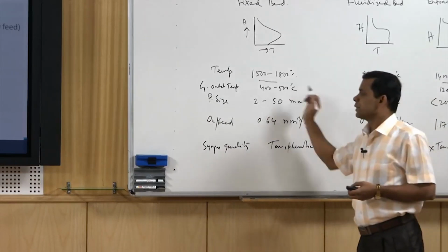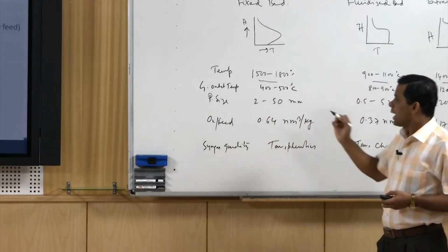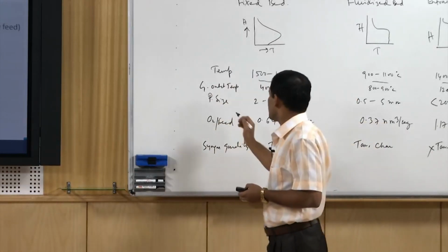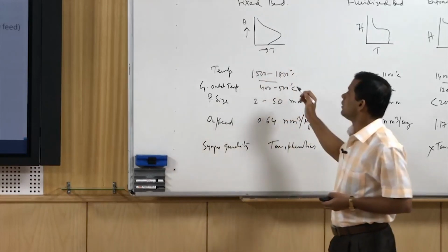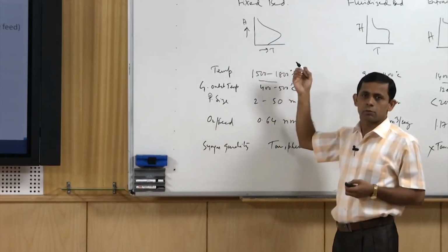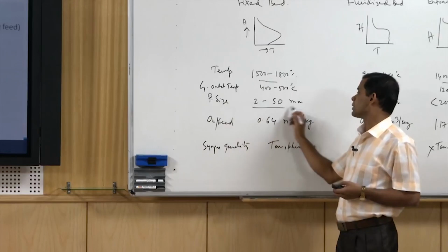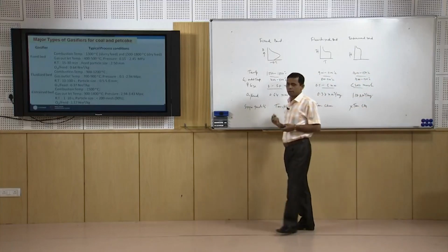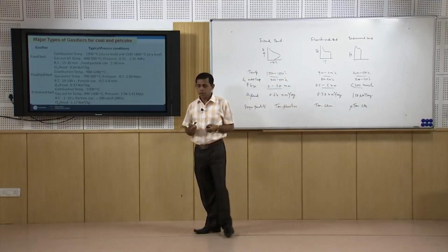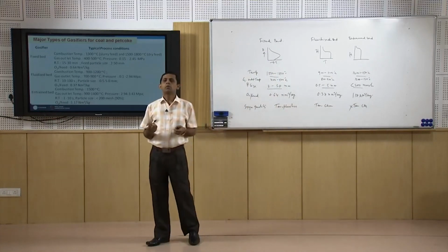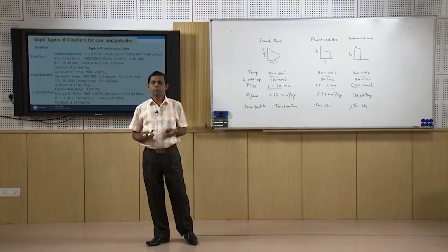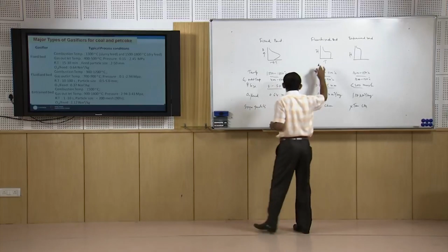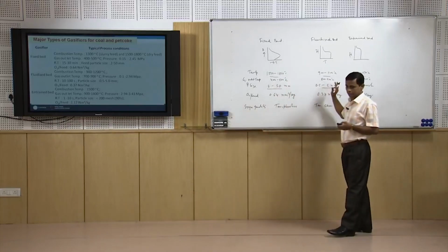The gas outlet temperature will also be lower, and as biomass and waste are lighter than coal, the particle size that can be handled for biomass and waste gasification will also be more than this size. Oxygen requirement will also be different because biomass and waste have more oxygen available in comparison to coal. But we will see a similar trend.